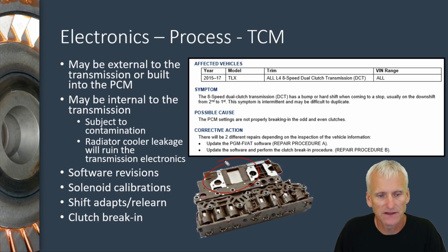One of the things, if you've got these internal TCMs, that you have to be really cautious of is contamination. Some manufacturers have had issues where radiator coolers break and then they mix ATF and engine coolant. And engine coolant seems to do a nasty job to the inside of a transmission. It kind of screws up a lot of the electronics.